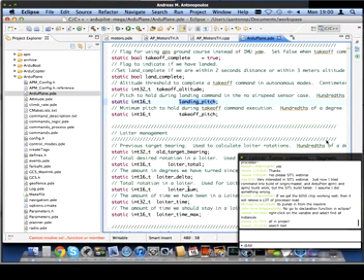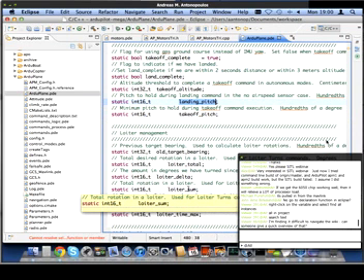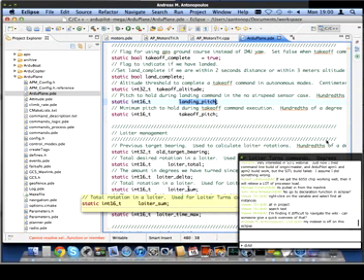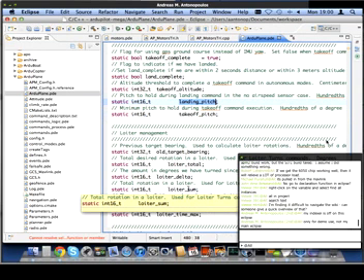Yes, there was code in the handle process condition command that set it, but the code was commented out, so it didn't actually ever set it there. But that was quite a long time ago. Let me just have a look at when that patch happened. That was in January. Doug commented out that code in January. So we haven't had landing pitch support without airspeed for quite a long time. It's always been recommended that you have an airspeed sensor, but obviously if you don't have one, then not being able to set the landing pitch is a real bug.